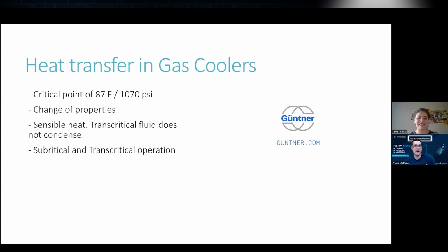Yeah, because now we have colder, we have less work on that high pressure valve. We got better heat transfer going into that flash tank vessel, that receiver. We could potentially have fluid coming out of the condenser now instead of going up into that transcritical mode where you're going to do more work in the system. So awesome.